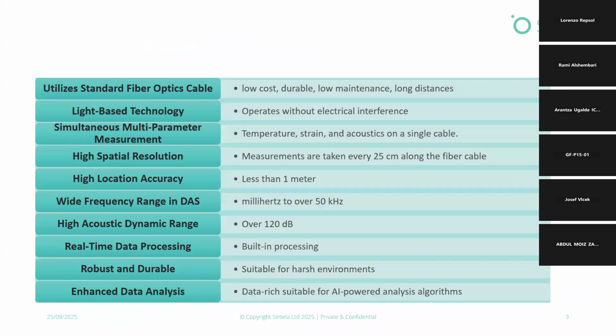Some of the features of this technology: it uses that standard fiber optics cable. It's low cost and it's durable. If we install and deploy it properly, it can provide data for many decades, as long as we have the interrogator at the right time. It's light-based technology, so there's very little electrical interference with other equipment. We can do multiple measurements of strain, temperature, and seismicity on that one cable. We do need different interrogators, but I'll dive into it a little deeper.